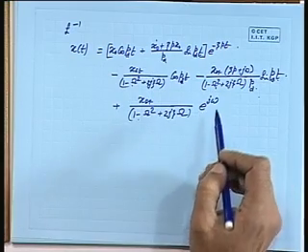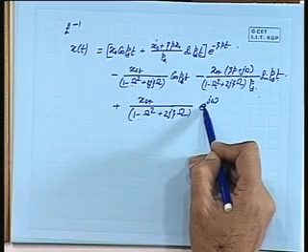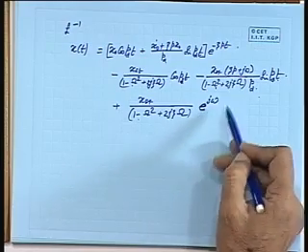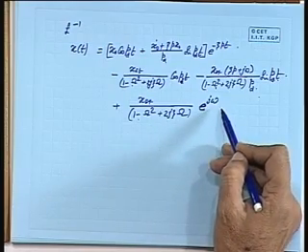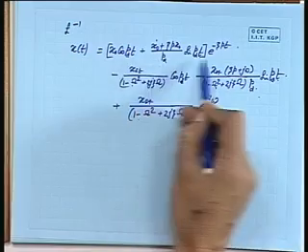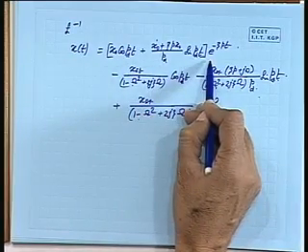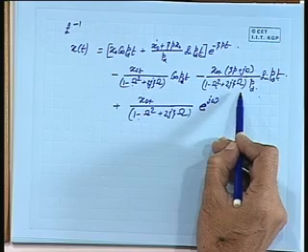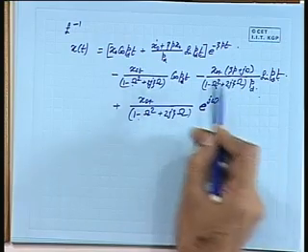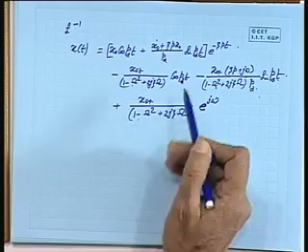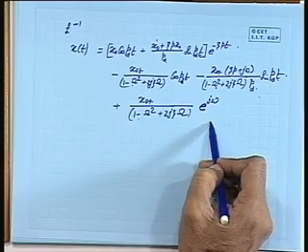In this part, the response is governed mainly by the forcing frequency here. Okay. So, this part we call the free vibration part. This we say is the transitional vibration, because it is changing from natural to forced, and this is the forced vibration part.